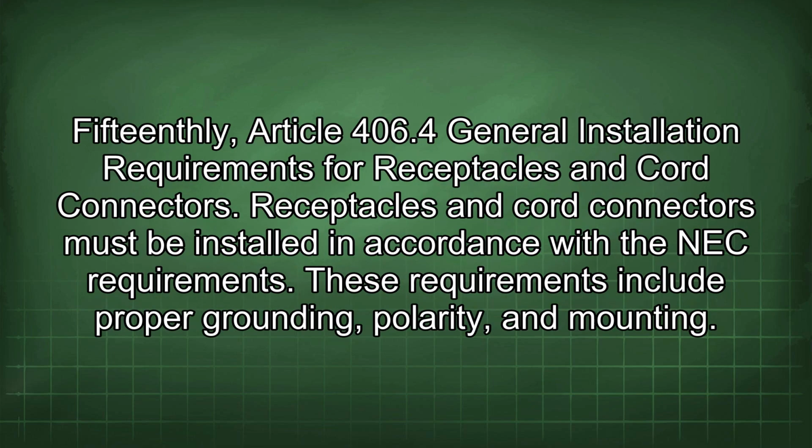Fifteenth, Article 406.4 General installation requirements for receptacles and cord connectors. Receptacles and cord connectors must be installed in accordance with the NEC requirements. These requirements include proper grounding, polarity, and mounting.